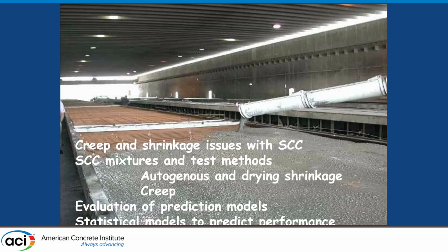What I'm going to cover today is, very briefly, background about creep and shrinkage and why we have to worry about this behavior for SCC. Then I'll talk about some of the mixtures that were tested under this program, and some of the test methods to cover autogenous shrinkage, drying shrinkage, and creep in compression. These are prestressed members, so creep is very important.